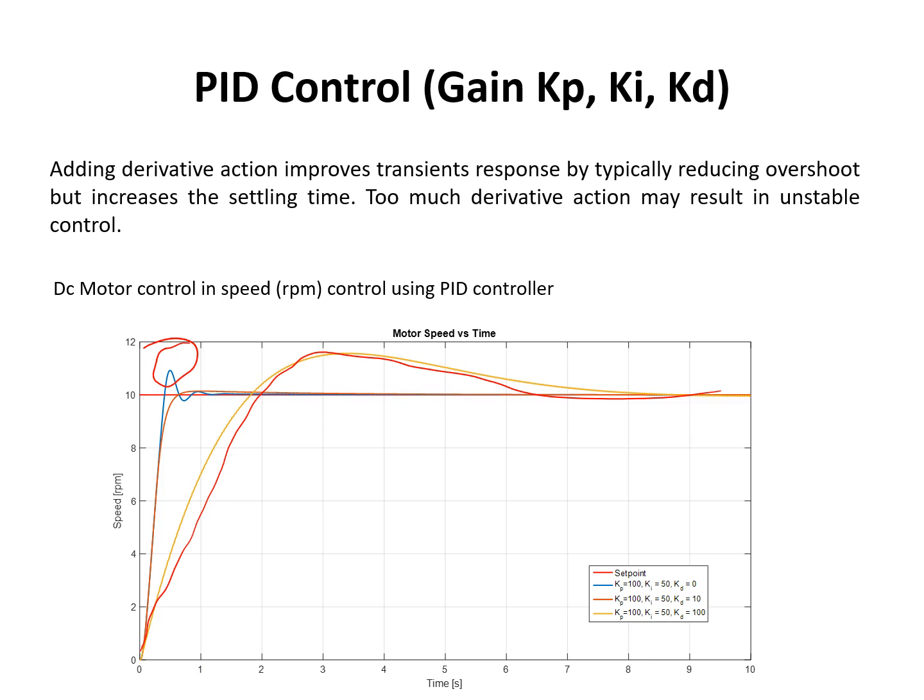And if you get to that, you can maybe increase the proportional term again and start increasing both of them until the system again has too high oscillations. At some point you might get a nice sweet spot where the system responds fast enough but does not have any overshoot. And if you have a steady state error which is not 0, only then will you add an integral term to your controller.